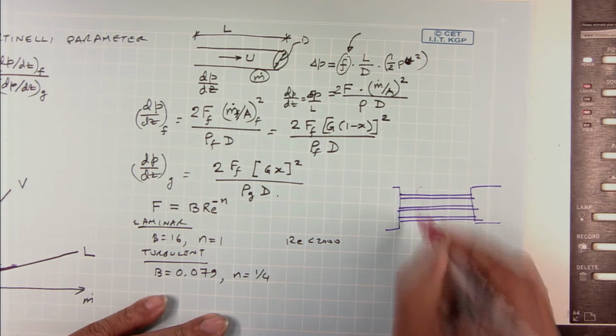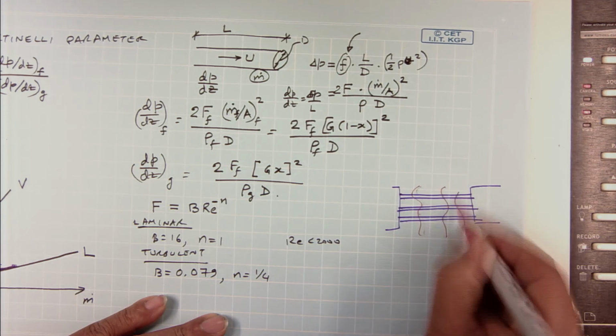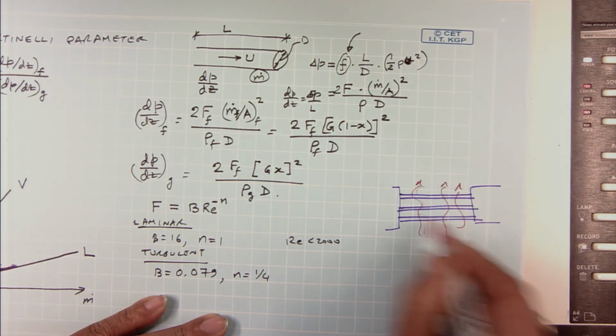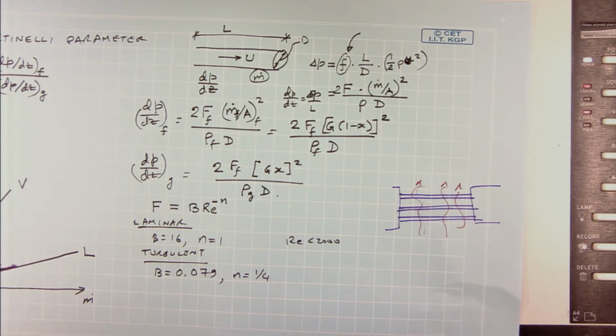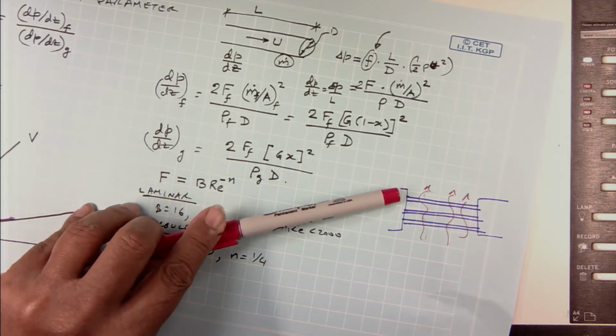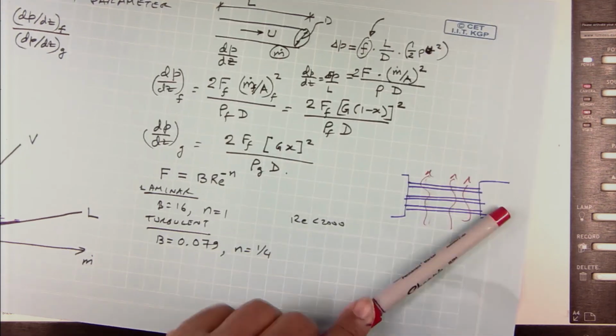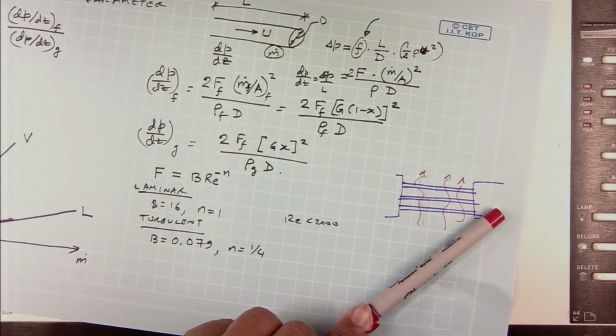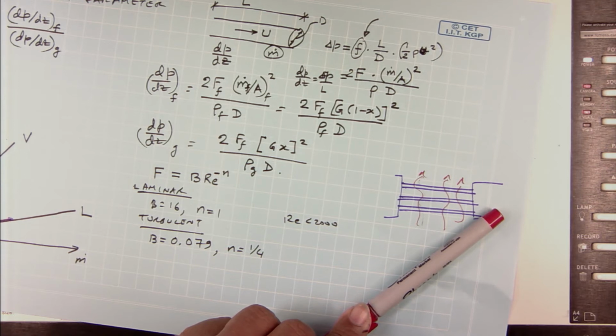If you have a gas fired burner or a coal fired burner, you have these hot gases at 300 to 500 degrees Celsius moving on top of these pipes, and the liquid is coming in, and on the other side I am getting out as pure vapor, because I cannot afford to have any liquid droplets in my flow, it will kill my turbine.